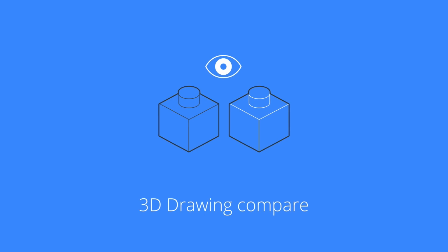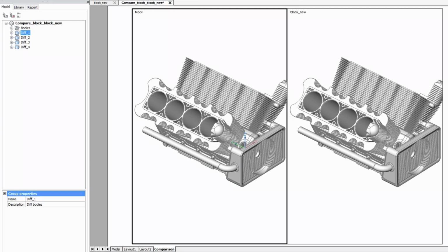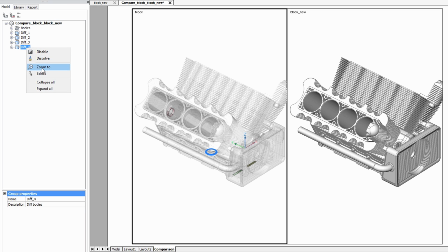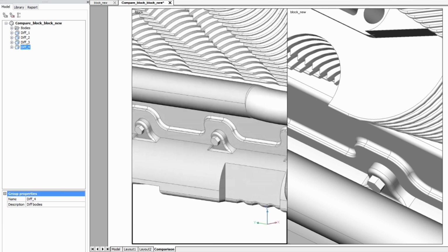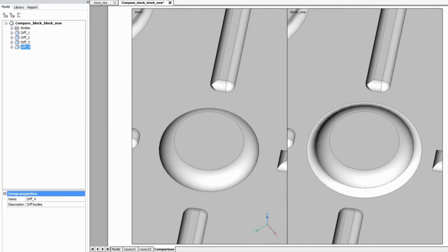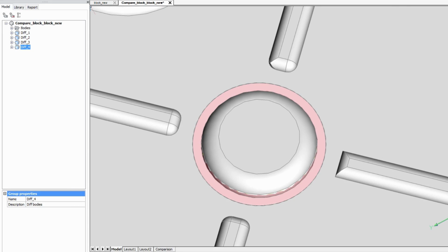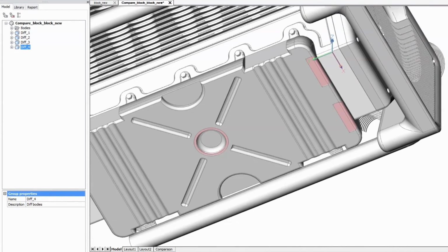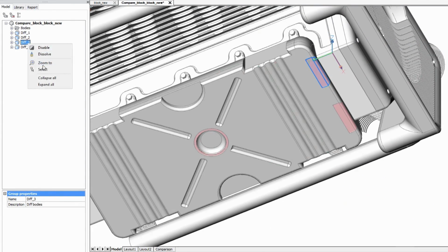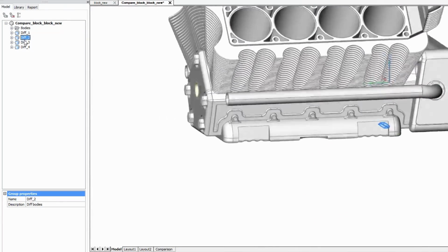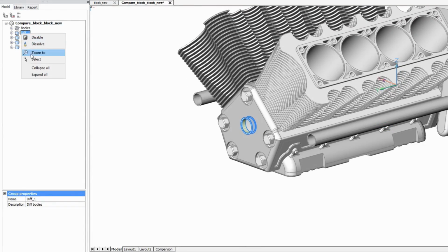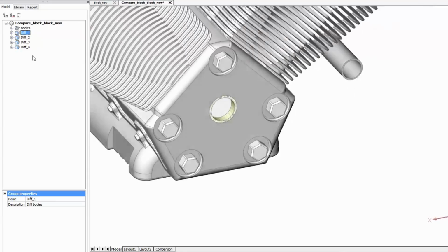3D Compare opens two drawing files and then reports the differences in 3D solids and 3D surfaces using color coding. This lets you quickly see the changes made to otherwise identical-looking drawings. The differences are represented as separate entities, displayed in two viewports. You have the option of leaving blocks and frozen layers out of the checking process. When you have the Communicator add-on, you can check differences in 3D models from other CAD systems, making BricsCAD a universal CAD model checker.